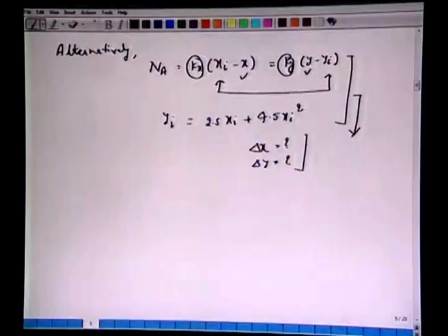So, that is a question we have answered. That is first another example on absorptions. And the more important here also to note that number of transfer units one can also calculate graphically as well as analytically. So, number of transfer units, if you recall, for a dilute solutions we have a very simple expression dy over y minus yi, all right.